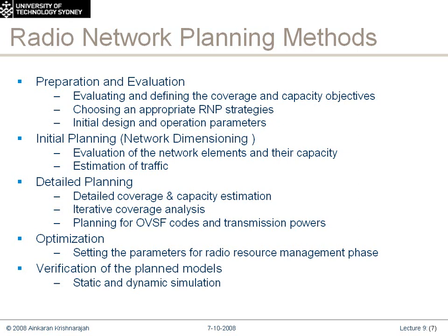So optimization is usually carried out by drive tests where it could be in a van with test equipment and people are driving around and looking at the signals and seeing how fast the network is running. Some optimization tools are quite clever. They work on themselves. They're automatic tools. You can leave them in buses and taxis and so on, and after a week you can pull them out of the cab and collect the data and then analyze them later. So there's a number of different methods around how that can be achieved.